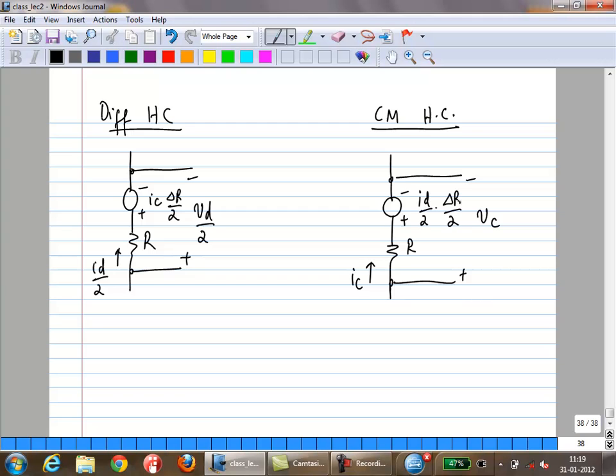Now this makes it easy, right? For example, if you have mismatch in the current, in the transistors, what is the transistor equivalent circuit? It's a GM, a transconductance. So you can say it's GM times V1, you have a current I1, you take two sources. Now you'll get cross dependencies: a delta GM times the other voltage. For example, current in one branch will not depend only on the input voltage, but the voltage on the other branch also.